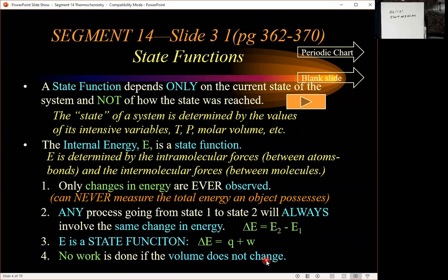Okay. Now, if you carry out the process so that the boundary can't change, in a constant volume calorimeter or in something where your volume can't change. A constant volume calorimeter is called a bomb calorimeter for a good reason. There, you could have some really energetic reactions going on, and if it's not heavy enough and sealed enough, it will be a bomb when that process takes place. So if you can't move a boundary, no work is done.